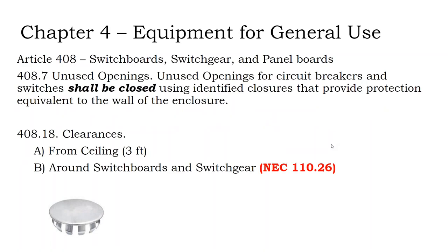So unused openings shall be closed. So what that means is if you drill into a box for your conduit run and then you end up not using that hole, there are plugs you can buy to fill that hole. You don't just leave a hole inside your electrical box, because you'll get wasps and critters nesting inside, which is a nuisance by itself, but could cause issues too. Panel boards, switchboards, and switchgear should be 3 feet from the ceiling.